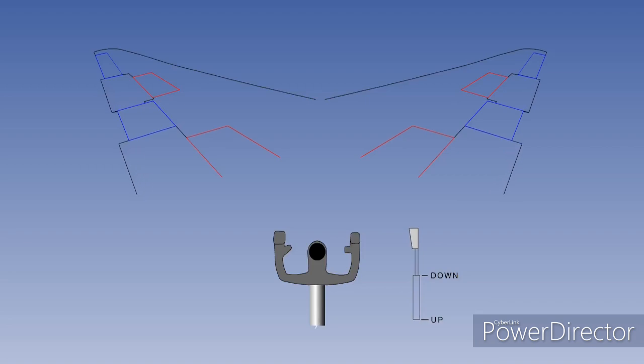In flight, the maximum angle to which the speed brakes can deploy is restricted to prevent excessive loss of lift and excessive buffeting. But as soon as the aircraft touches down, there is a need to remove as much lift from the wing as possible so that the wheel brakes will have maximum effectiveness. In addition, there is a need to increase drag as much as possible.